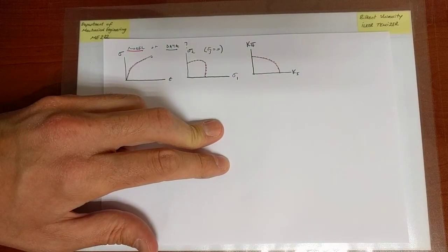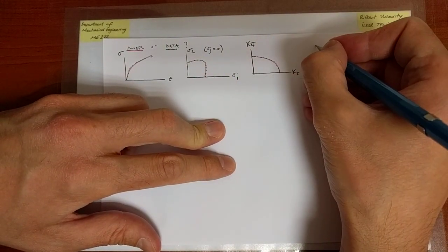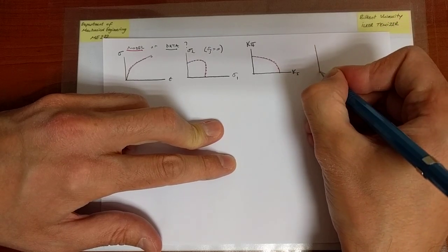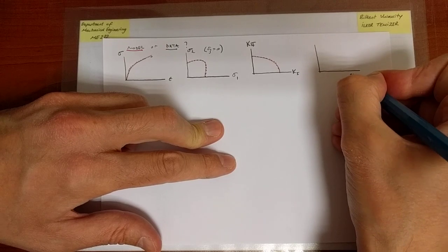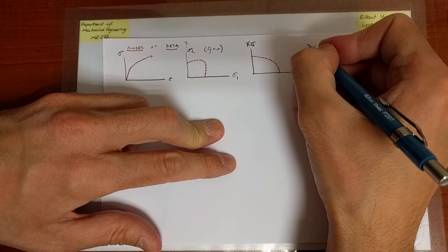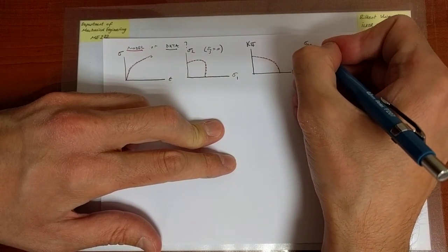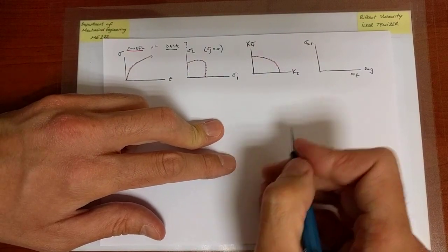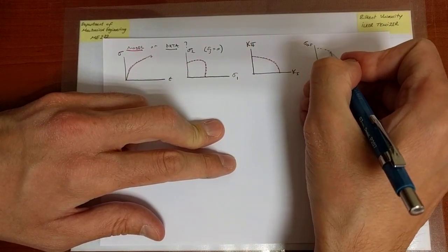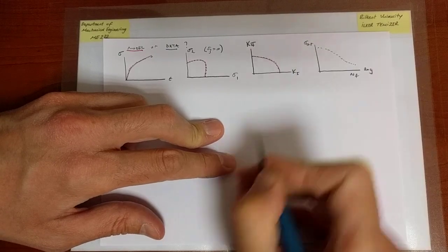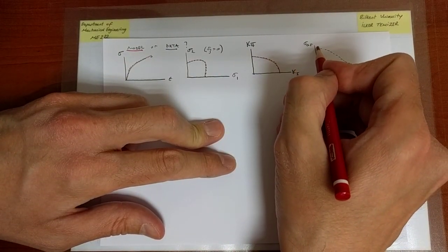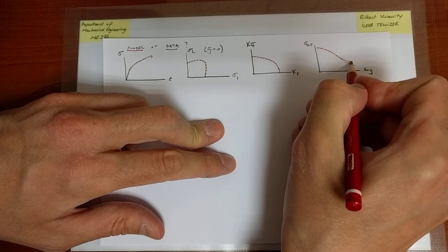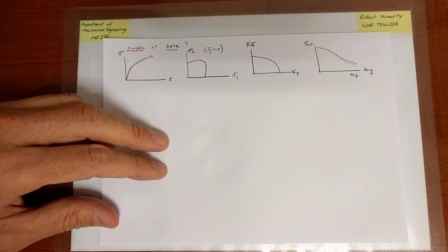Presently, the scenario that we're facing is one that has to do with the question, what is the number of cycles to failure on a log scale versus a linear scale for the stress amplitude? What is the number of cycles that leads to failure, or what is the fatigue life versus fatigue strength relation? And again, we can fit a curve to it.